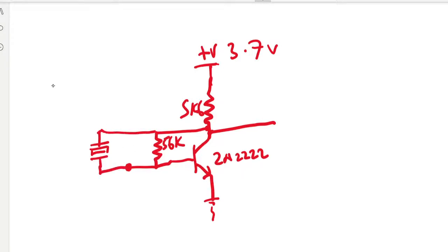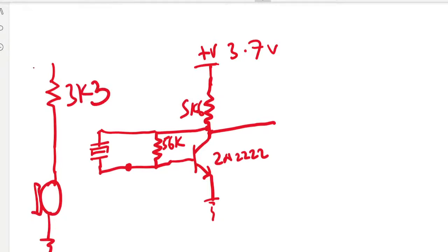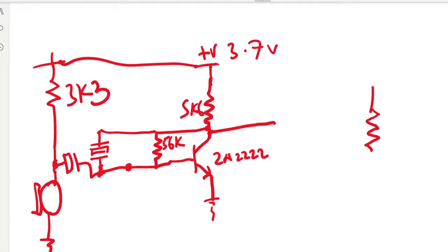And when you have this crystal, just bias the condenser microphone this way, ground. We use 3K3 here. This is also positive, so you can just tie them together. All right, and then from here, we have a capacitor to here. So if you like, you can add a volume control over here.